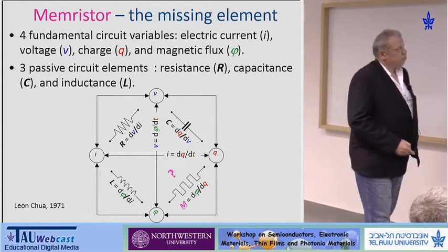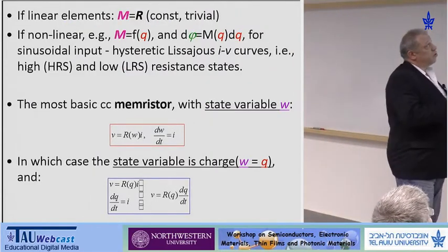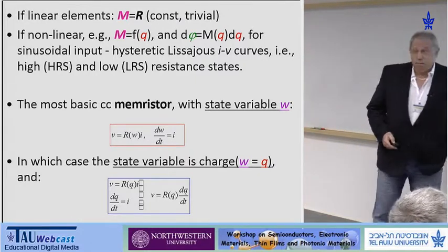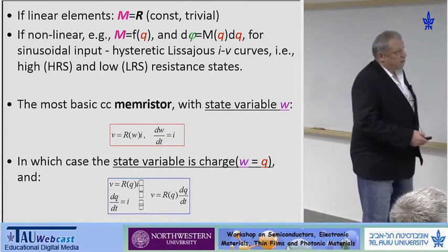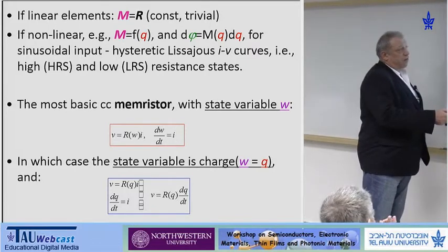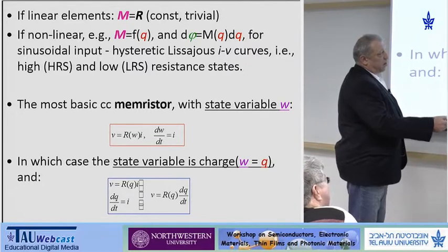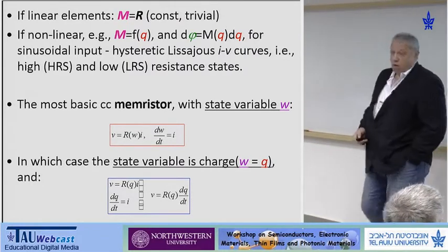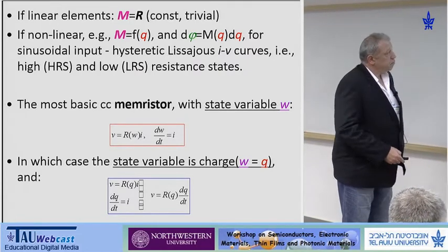So, in fact, of course, in the linear case, the memristor reduces just to the simple resistance. However, if a memristor is a function of some state variable which is time-dependent, for example, as defined here, and if we take an example where the state variable W is defined like that, then obviously from the definition we understand that we talk about charge-dependent resistance.